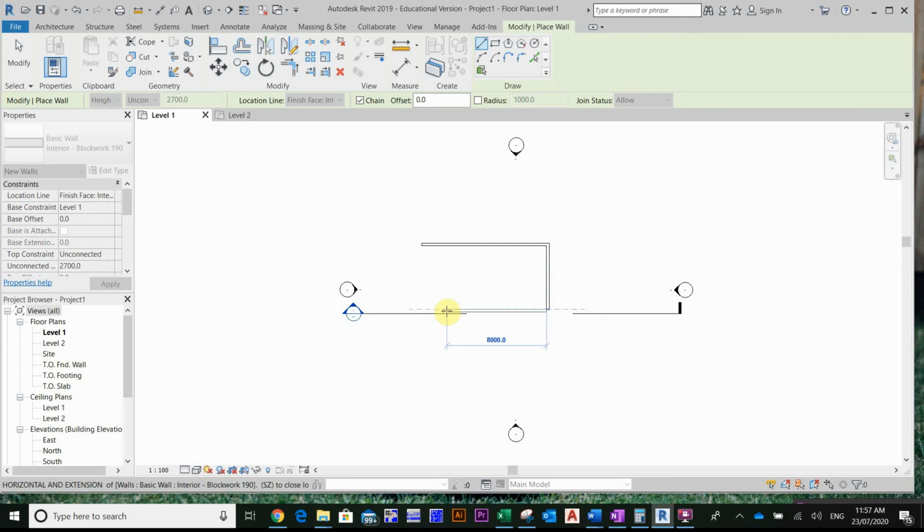And you'll notice that I'm going anti-clockwise in the way that I do this. That's so that the inside is always to the inside of my house. Otherwise I'd have bricks on the inside and plasterboard on the outside. Okay, so I could type in 10,000 again, or I can get the computer to predict what I'm trying to do. And to do that, I haven't clicked at all. I've just hovered over and I'm allowing it to do some thinking for me.